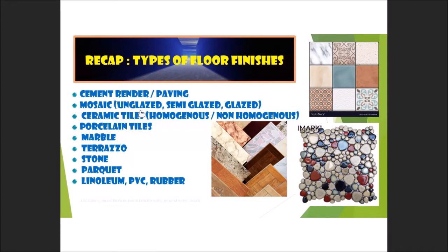Okay, so you can see here unglazed. This one means the surface is not so shiny and then not easily clean. But if you have glazed tile, normally this one is used as the wall finishes because it's easily clean. But for the floor, we may use either porcelain and ceramic. Porcelain is normally more expensive than ceramic, and then the manufacturer detail also different. Okay, but the difference between homogeneous and non-homogeneous are normally according to the material.